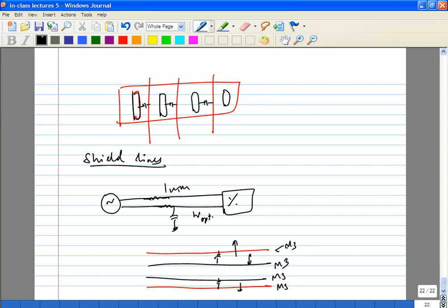On M4 or M5 on top of this, you typically don't want to cross. You don't want to cross these two sensitive lines at all. Now there may be cases where you are forced to cross, in which case you make those cross lines extremely small, extremely thin, and short. Obviously you don't run lengthwise, you run perpendicular. That is one thing you can do.